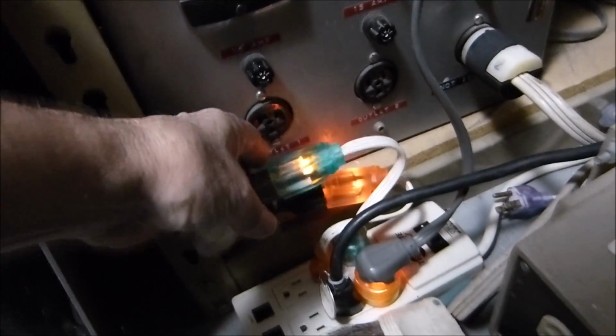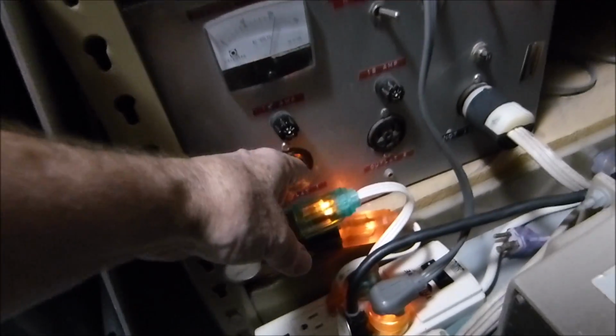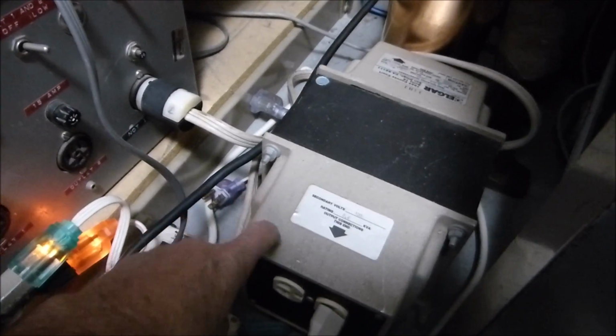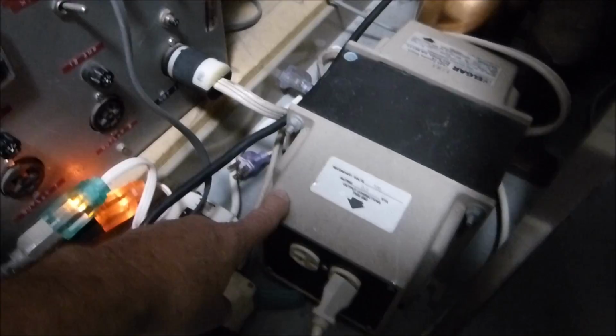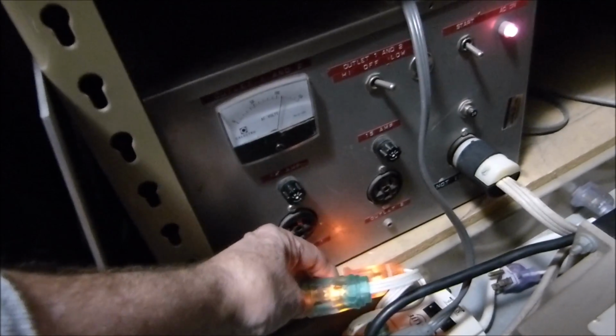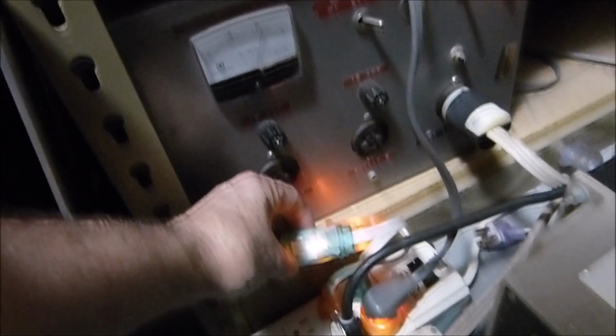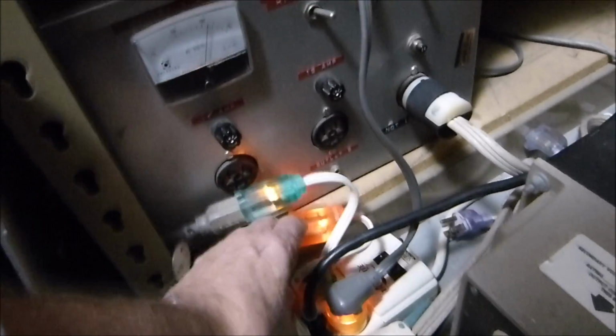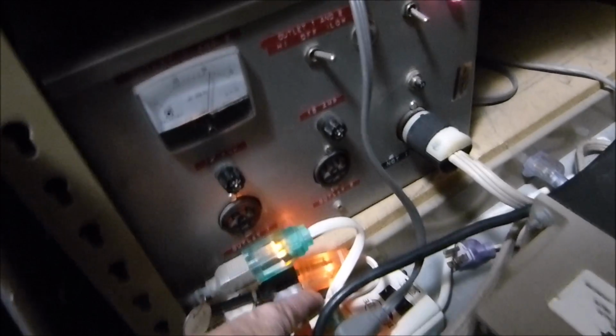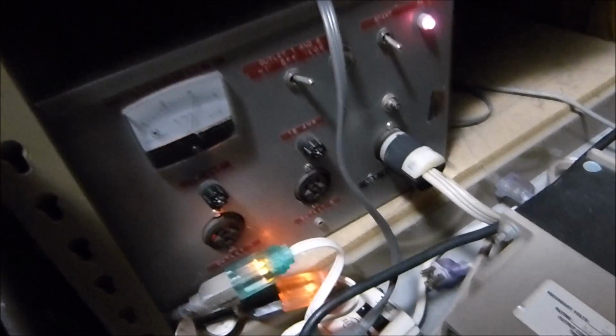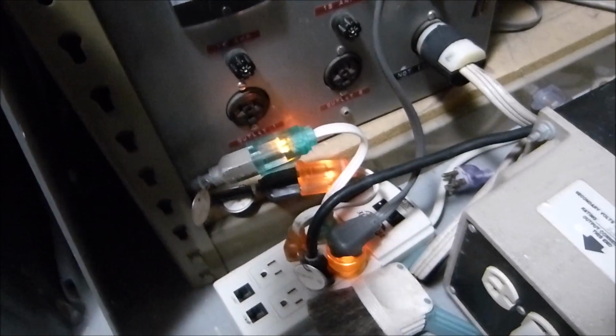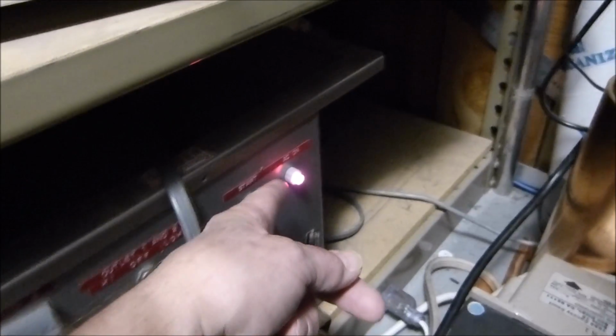Speaking of letting you know it's on, I use these things right here too. Everything on my bench goes through this isolation transformer right here. That's a 2.4 kVA isolation transformer, so it's pretty hefty. But I also like to use these because it reminds me that there's power there. These little neon lights in there, they don't do anything. They're just a little piece of about 6-inch wire, but that's why I put them in there. I make sure that all my lights work because it could save my life.